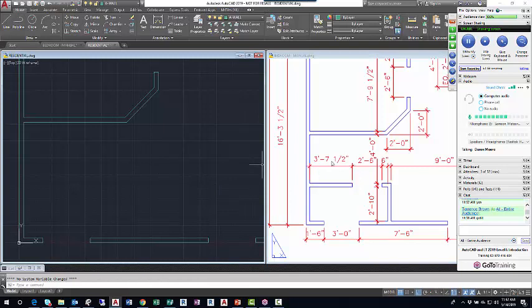My personal preference is to take the path of least resistance, much like water would in a sprinkler pipe. So I'm going to offset the bottom line of the large closet down the screen 4 feet. So I'll go offset, make sure I get the right screen selected, offset 4 feet, enter. Left click this horizontal line, move down the screen, left click.